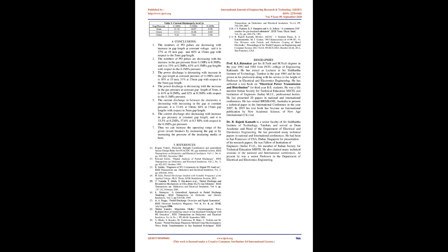It is observed that PD is more predominant in the negative half cycle at the angle of 288° to 324° and in the positive half cycle between 0° to 36°. As the gas pressure increases, there is a decrease in the PD activity. All this data we get from 2D PD graphs. Similarly, the following 3D PD graphs for 10 mm and 15 mm gap lengths have been shown. Figure 7, 3D PD graph of 10 mm gap at 0.3 MPa pressure.